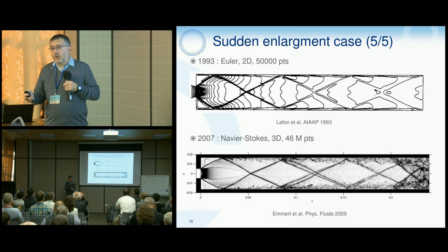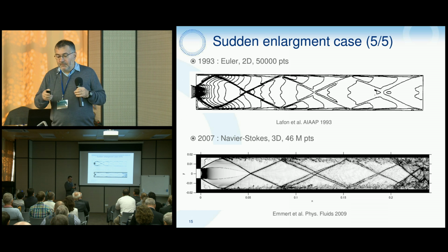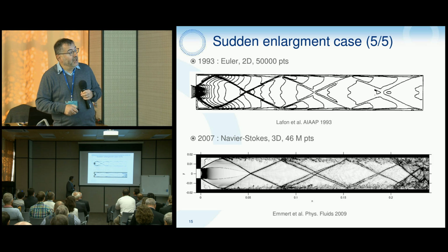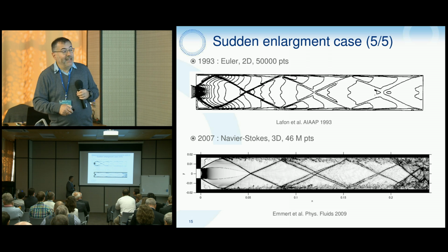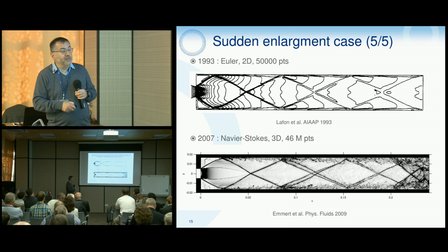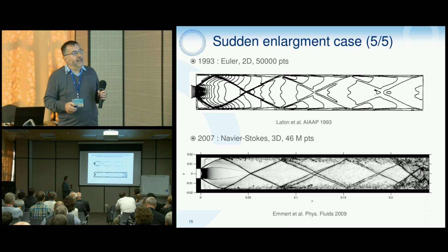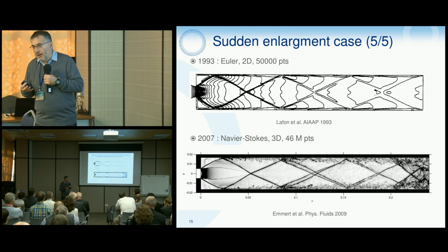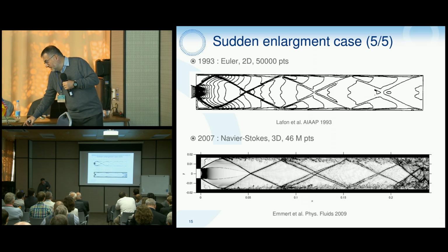In the Anderson paper, it's very well analyzed. In fact, you have all these unsteady phenomena because you have communication between this cavity and the corner pressure through the boundary layer. Because the boundary layer is not subsonic, you can have communication, pressure waves coming upstream through this corner and causing some destabilization. So the Navier-Stokes approach was needed in order to retrieve this kind of situation.